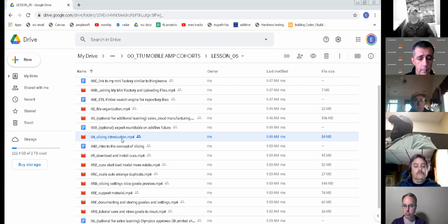All right, so we go through all of those things. We talk about support material, and of course, we talk about orientation, your object, and how you set it up on your print. Now, one of the things, if you want to get into a little bit more advanced stuff, is that, let's just say you're making a cylinder. The normal tendency is just to set it on the build plate and let it print straight up. The quality looks great. It'll print smooth and quick, but you have that Z-axis weakness.